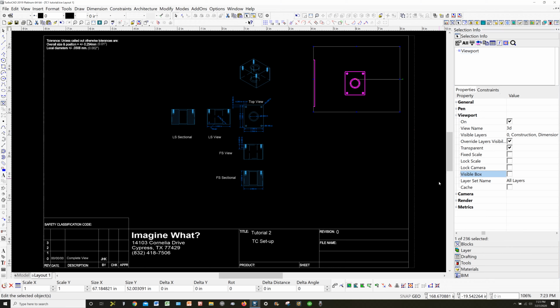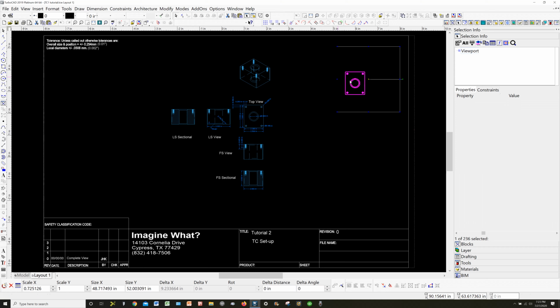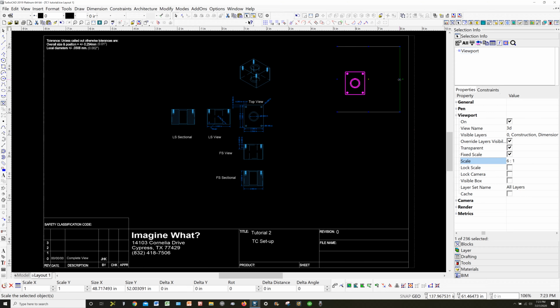I always forget, but I don't want the box. I want a fixed scale. It says right now it's at 6:1, so let's just make it an even 6:1. And there was an overlap in this, where it was seeing something that we're not needing in our view, so that's why I locked the scale, so I can go ahead and basically crop it without changing the size.